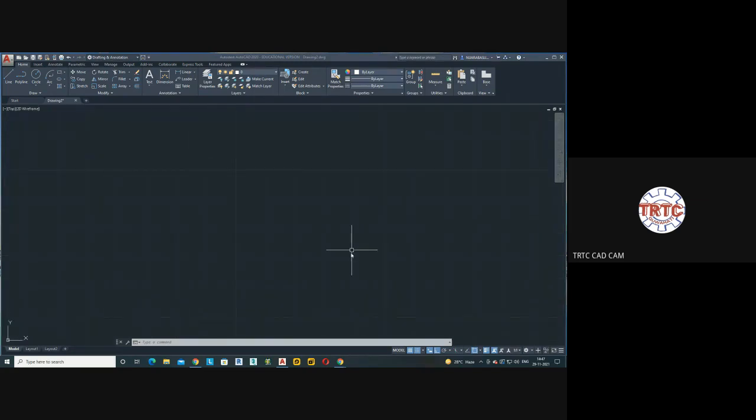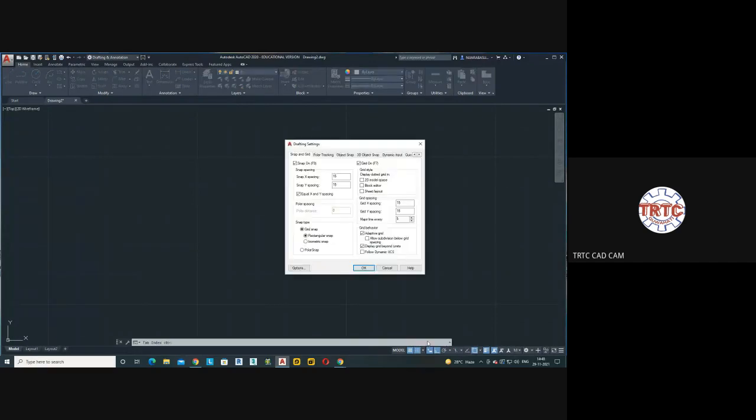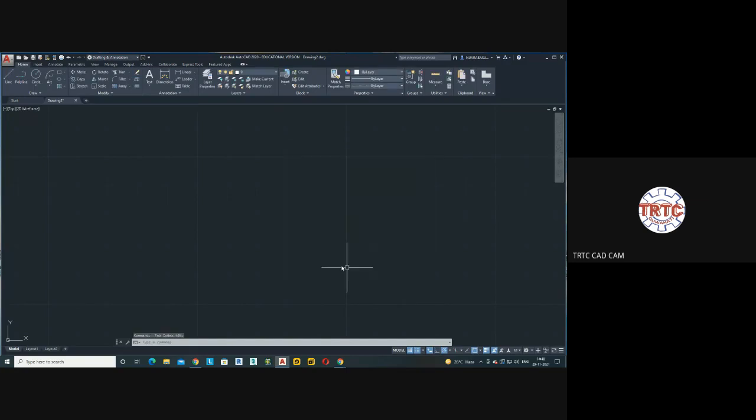Okay, so that is snap, and you can go for this polar snap. I will show you what this isometric snap is. If I go for polar snap, see polar distances. Let's say I'll specify 50. Next to this grid snap, polar tracking is there. I can turn on the polar tracking and make it, let's say, 45 degrees. Go for okay.